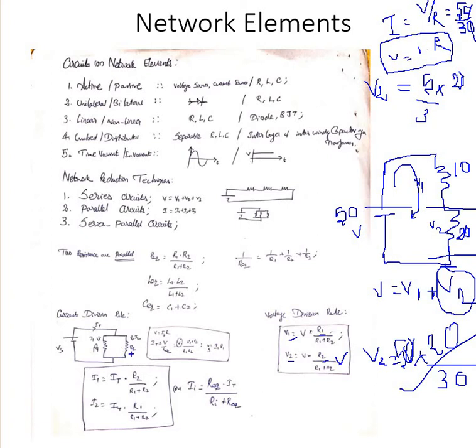Now the current division rule. Similarly, you have seen that the flow of current I is common, and here I1 and I2 are divided. Why is it divided? Because it's a parallel circuit. Then what is the current flow in I2? Can you find it, similar to the formula? I2 is equal to I into R divided by, what is in the denominator? R1 plus R2.